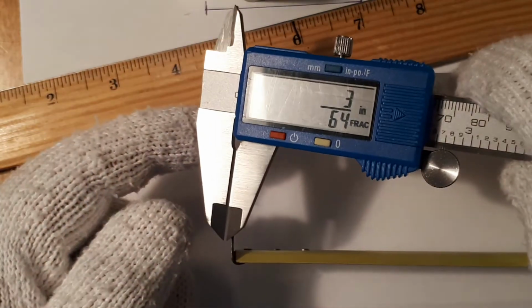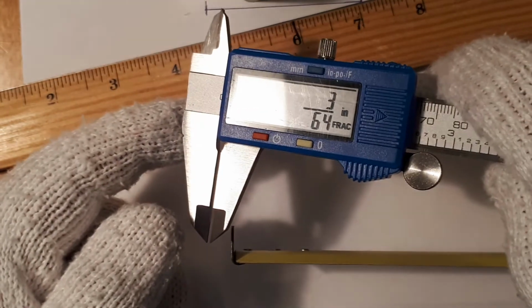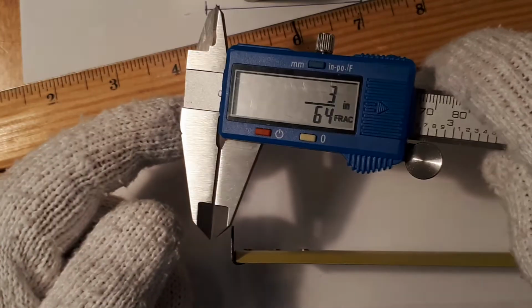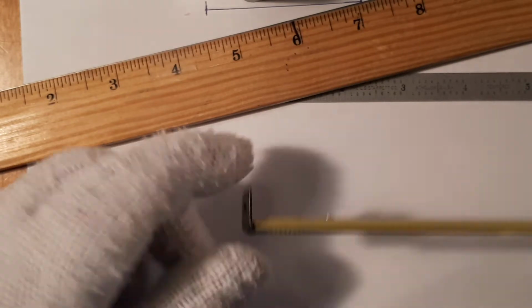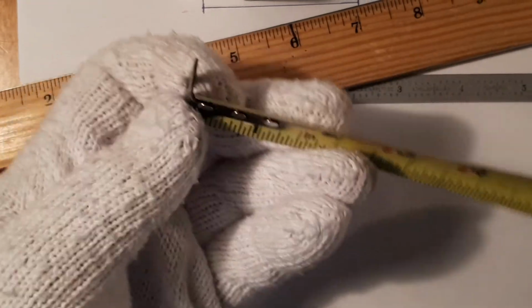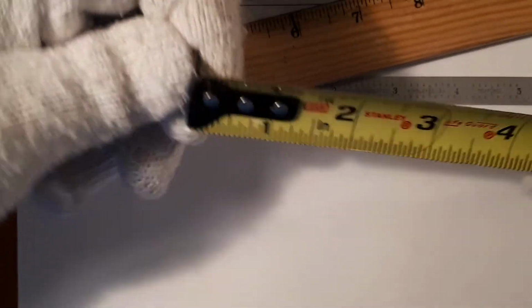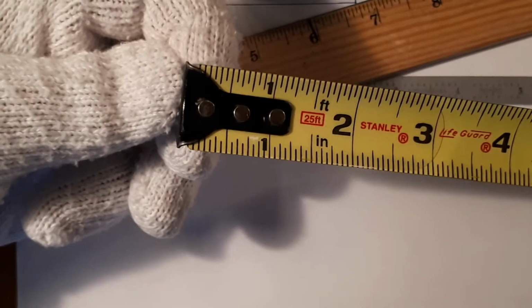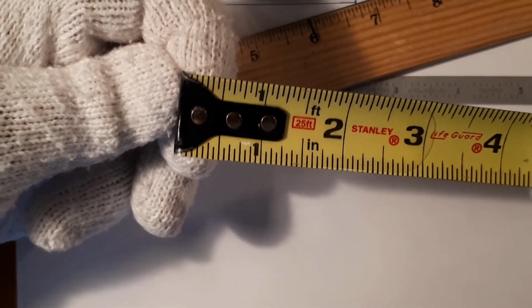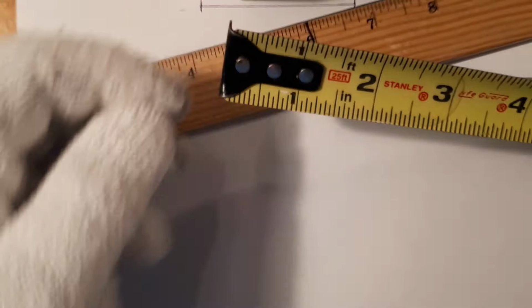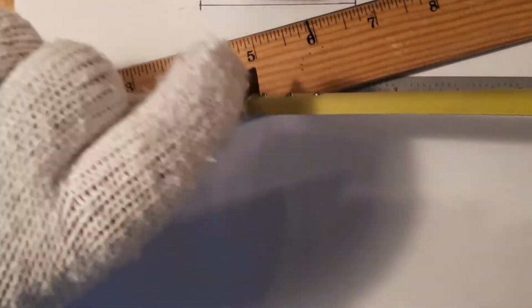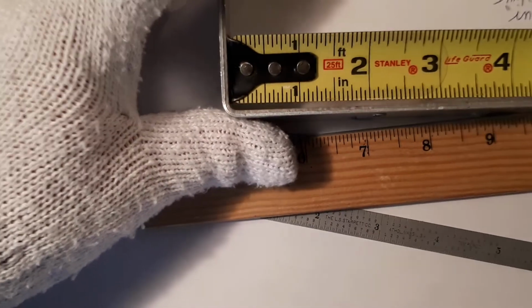And I measured the tab to be 3/64 of an inch. What that means is the distance that the tab will travel as it readjusts to 0, going back and forth, is 3/64 of an inch, such that the 0 changes from that surface to the inside surface, depending on how I am making the measurement.